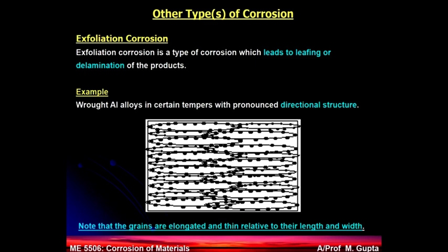And many times when you lay the underground pipes, for example, or tunnels, you have to check the soil to ensure that these bacteria do not thrive there. If they thrive, then you have to either do the bituminous coating or cathodic protection to ensure that their effect is mitigated. All right? So this is in summary of macrobiological corrosion and microbiological corrosion. Any questions so far for these two types of corrosion, biology-related corrosions? No? All right. Other types of corrosion.